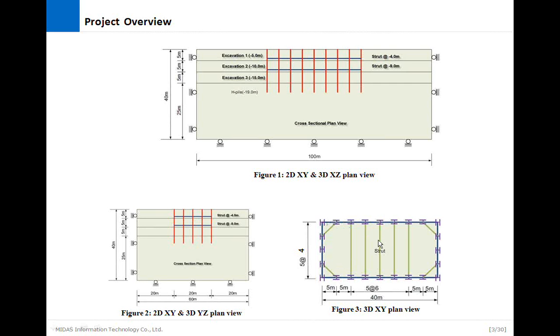The struts will be modeled using truss elements, and they will be round in shape, and the wales will be rectangular in shape and modeled using beam elements. We will model the ground using solid elements, since we won't be applying very hard external loading.